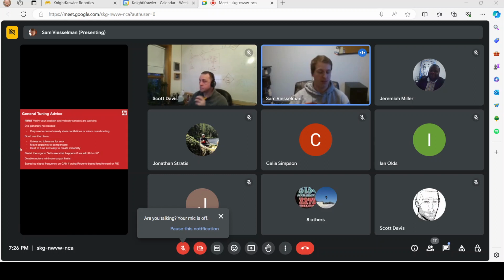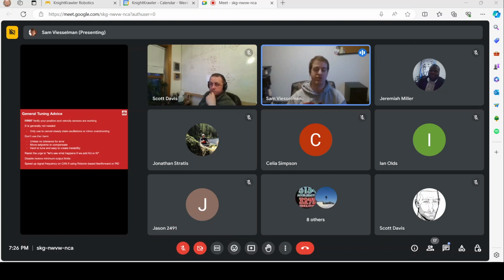One of the reasons a lot of people will add the I is because let's say you're trying to move your arm to 80 degrees and you find that you're at 79 degrees and you're a degree short all the time. So you add the I in to try to get that last 1 degree. Something I might suggest is just moving the set points to compensate for that. So rather than making your system more complex and dynamic, you just adjust it and say, well, I guess 81 is the new 80. If you're very CAD driven and math driven, that can be a little bit of a fudge factor in there. But it can be easier than trying to make your control system more dynamic.